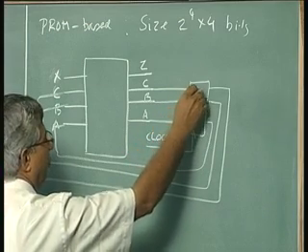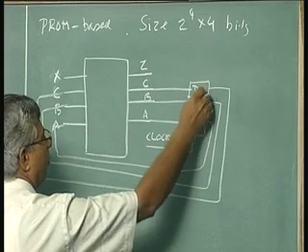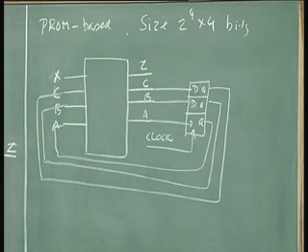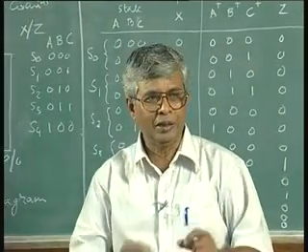Each is a flip flop, all clocked at the same time, so I am combining. You can also use a 4-bit register and use the first 3 bits, that is also possible. You need not use 3 individual flip flops.